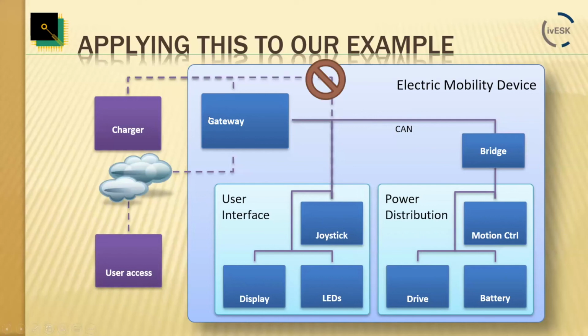And if you compare this to automotive, this is why they came up years ago with the onboard OBD port. The OBD port was originally designed to be a single point-to-point communication, because it was also designed to be a firewall into the vehicle, to protect the internal networks from direct access.